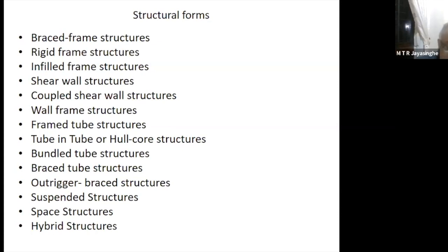So Mr. Senaka also knows. Dr. Pradeep uses it a lot. So I have invited Dr. Pradeep to do a lecture. But the most important thing is when you are buying the steel decking material, it's very important you buy a proprietary product, and some best products would be something like BlueScope, which is a very old, well-known name. Don't go with cheap products when you are using deck material.